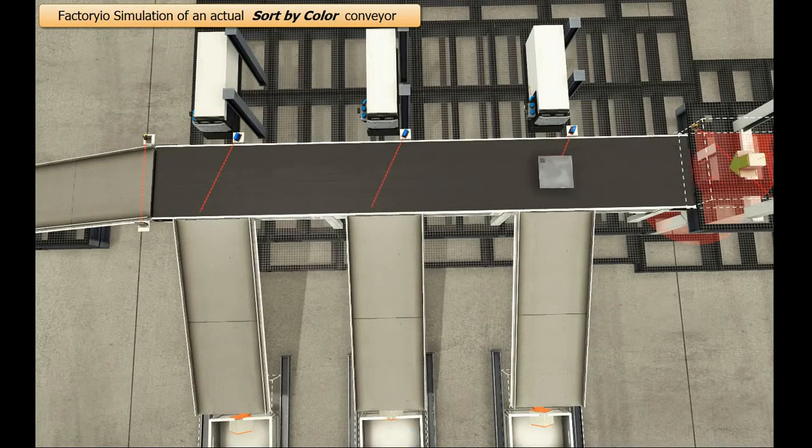Again, like I said, I've chosen the belt speed that minimizes any negative effect caused by selecting either part present or the encoder, so they'll stop in approximately the same place, and you're going to see that in a minute for the encoder.